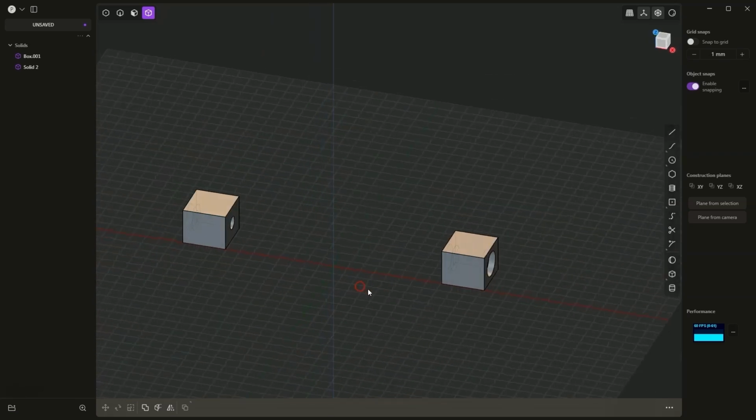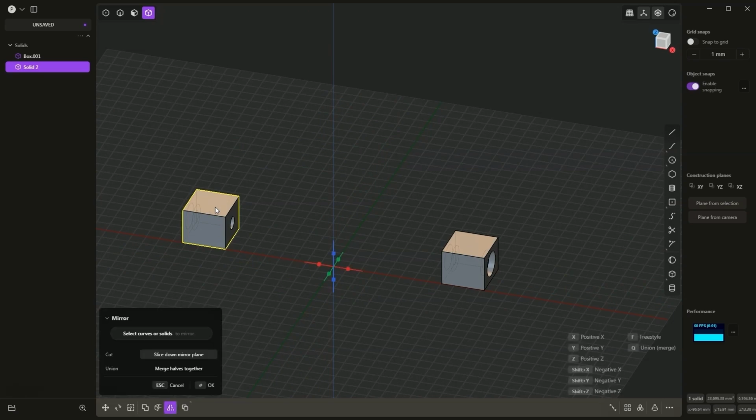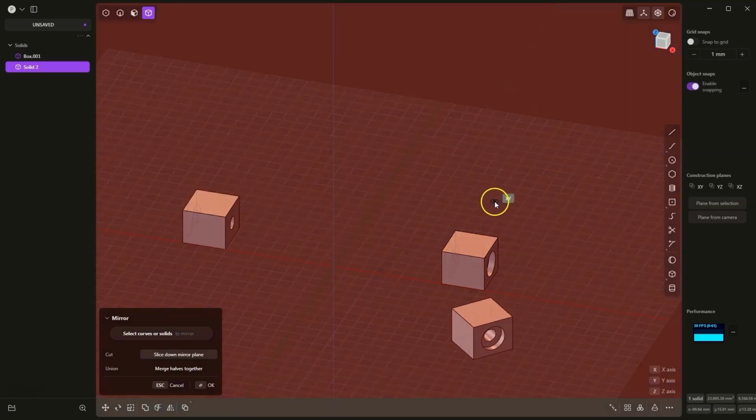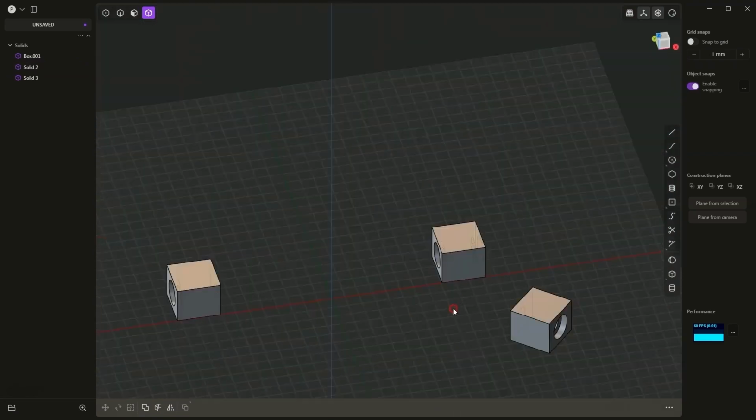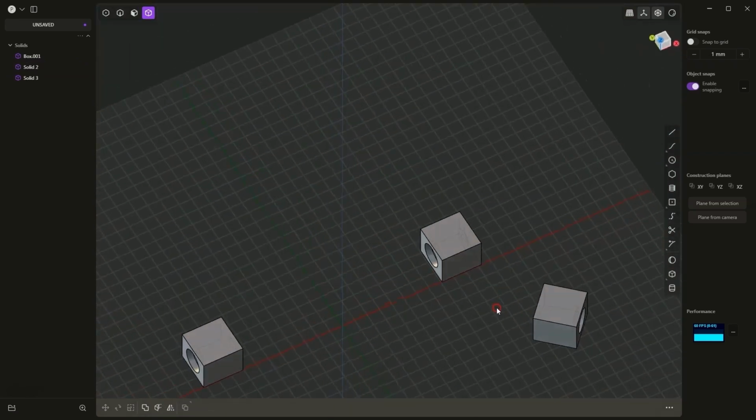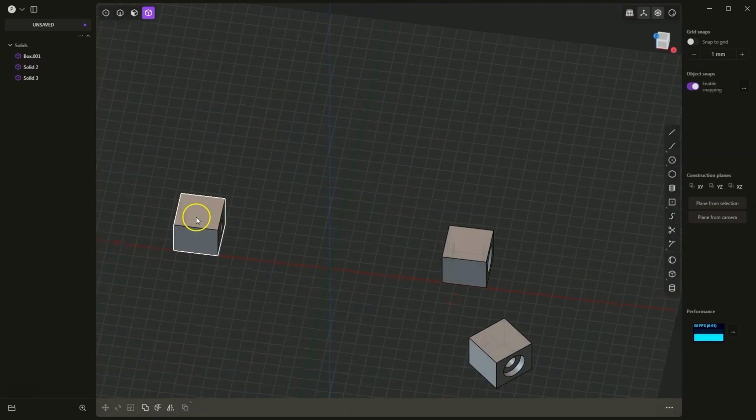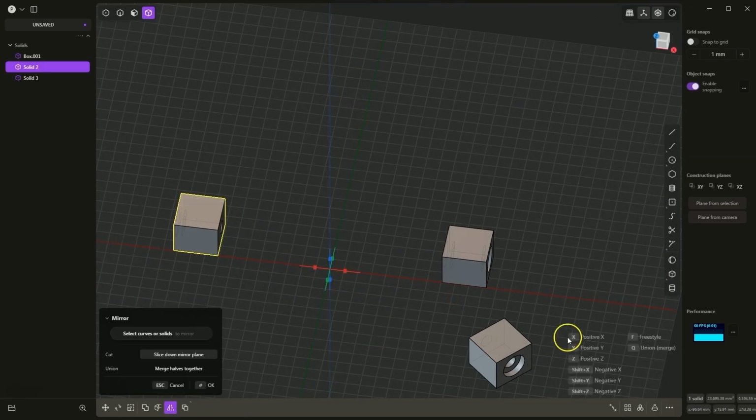When it comes to adding a mirror feature and defining your own mirror plane, we can actually place this plane anywhere. Now I press the F key and will specify, for example, 2 mirror points. I accept, and now this mirror operation has been performed this way. However, more often we will perform this mirrored feature relative to some characteristic points of geometry.